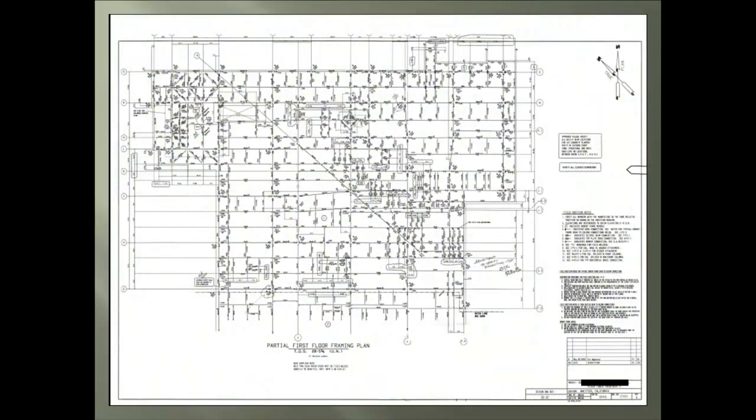We move to the second item of this segment, which is the column found in the shop drawings. Once again, looking at the first floor framing plan, we will focus on this area for a closer view of the column in the discussion. As we see the area closer, first, this is the column we will break down. And here is the important call out for this column, which reveals the size W14 by 665 and piece mark number 1003A.